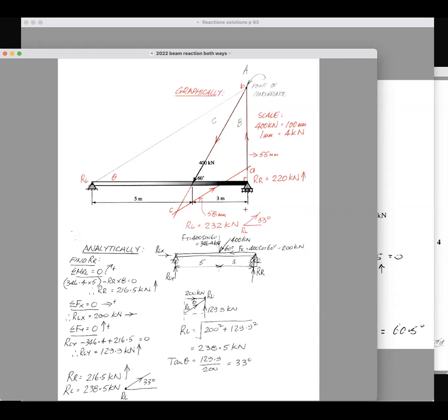So I'll just go through the analytical process again very quickly, and then I'll show you how to do the 3-force rule to determine the reactions. And you'll see that the 3-force rule is much easier than this, unless you're interested in doing it mathematically. You'll get exactly the right answer mathematically, but if you do it graphically, as you know, you'll get a tolerance of 10%